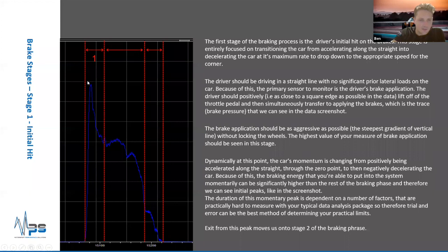That's not really what we do, but we look to make sure we have this shape first in our driving, and then through iterative testing and data collection, we can quickly work out rough values, rules of thumb, as to what we expect this peak could be achieving. So again, I talk a lot about shape, brake shapes, and most engineers will.